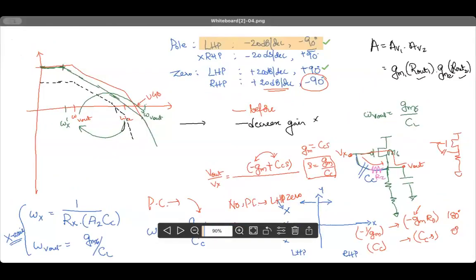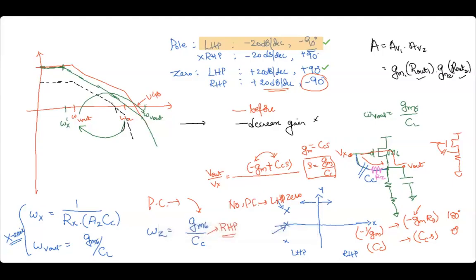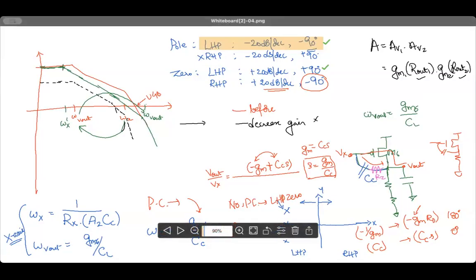Now we are trying to reduce A by a significant margin. The moment you try to reduce A, your accuracy is hit and you do not want to have that. What's the alternative? The alternative would be to somehow have stability by using compensation, and that compensation is a Miller compensation that we discussed, where we put a Miller compensation CC between the output stage, input and output.